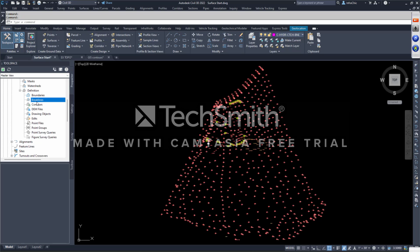I'm going to touch on break lines really quick. There are multiple different types of break lines. There are 3 different types. There is your standard polyline break line, elevated and not. There is a 3D break line, which is your 3D poly. So your 3D polyline, which can be converted to a 2D poly by typing in convert 3D polys. Or feature lines, which is Civil3D's version of a 3D polyline. Much nicer, much easier to manipulate. You're not having to use the properties dialog box or a command line interface to do so. But we will come back to that.